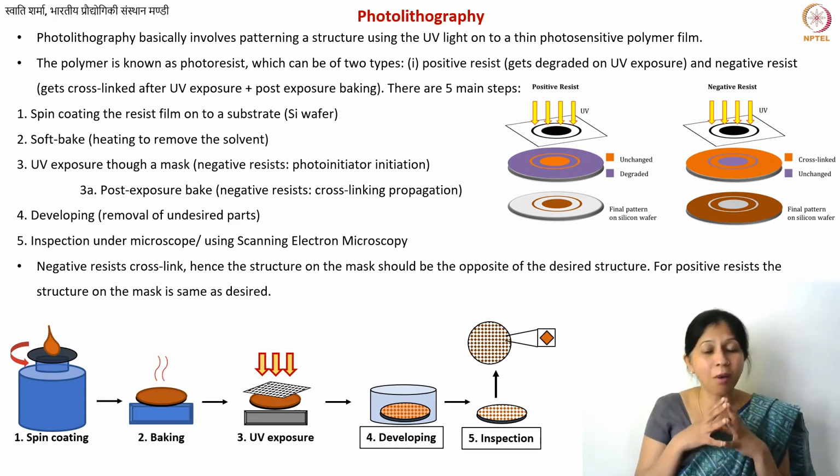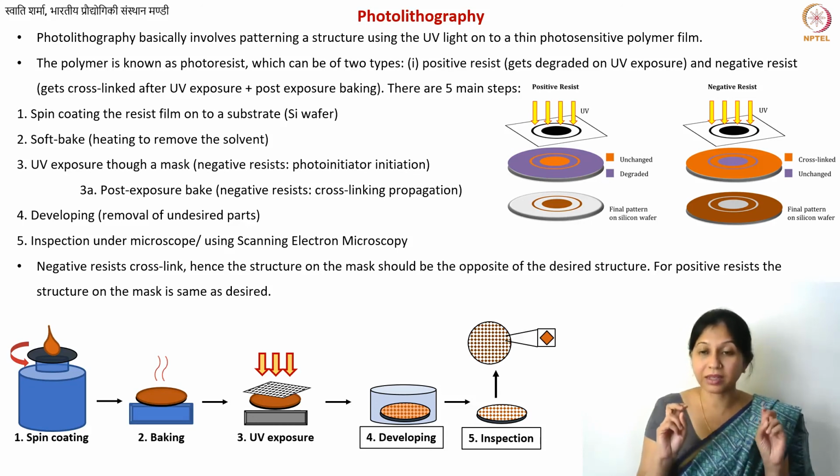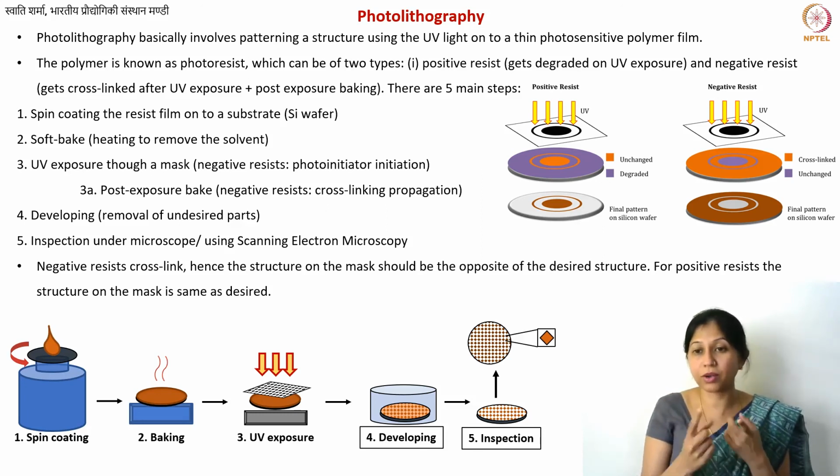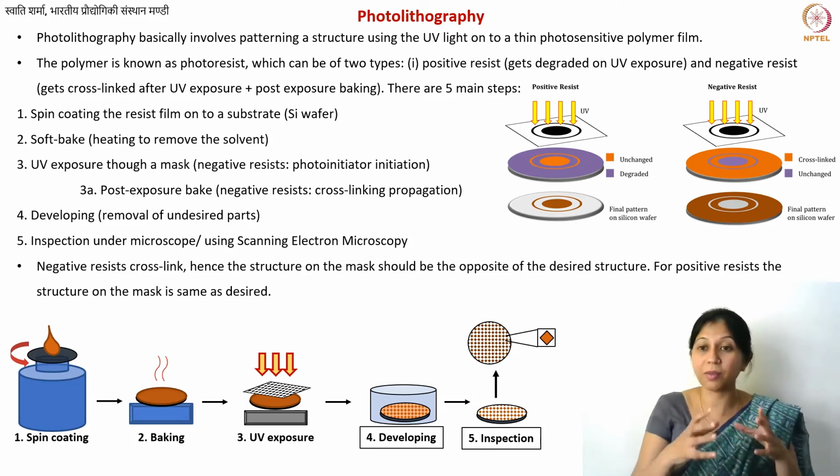These are the most common parameters that are used for glassy carbon based microfabrication. Number one, you use silicon wafers with or without oxide films, depending upon your application. Number two, you use a photoresist, which is a phenol formaldehyde resin, a negative resist SU8, and it is available in different viscosity. You use 900 degrees centigrade pyrolysis temperature, a ramp rate of less than 5 degrees per minute, and an inert environment for pyrolysis, and now you get your carbon structures.